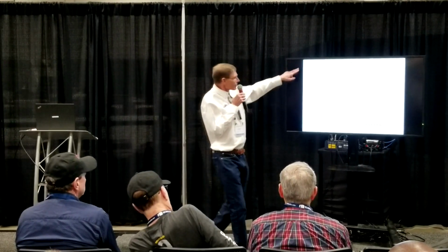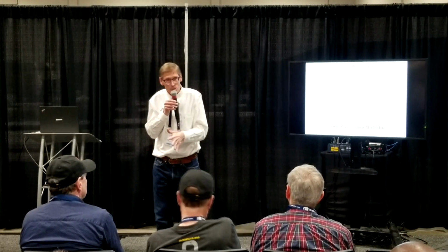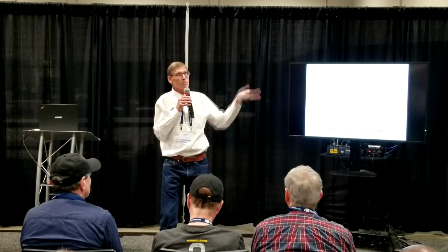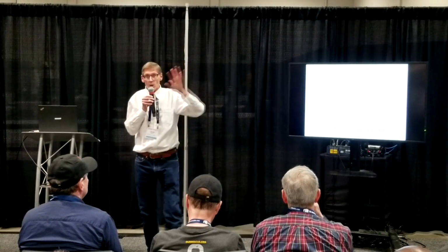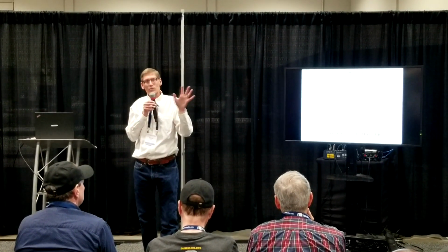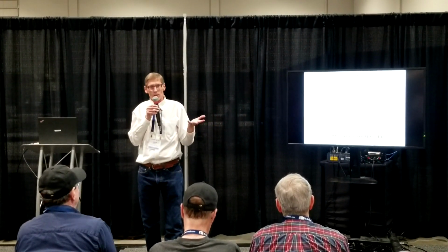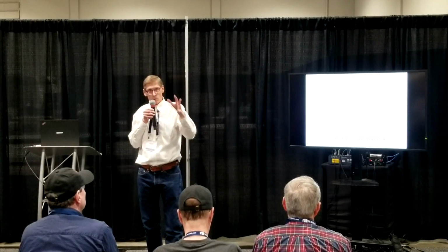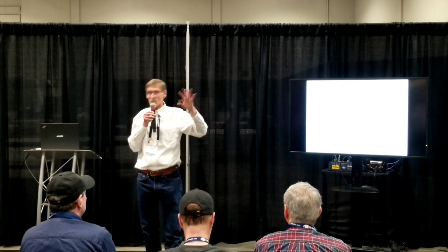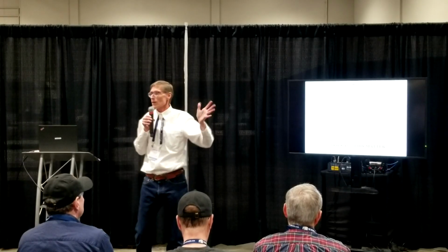So now we understand why our cables at high frequencies drop in impedance. We understand why they go up at low frequencies, because if VP is going to zero, that makes our impedance go up. Okay? We know how to properly characterize an analog type cable at low frequencies using open short, so that's a realistic way to help us understand what our cables are doing. We know what those numbers are comprised of. We have to have R, L, and C. Measurement gets R and L, or the swept characteristics, and the other one gets the X sub C, or the capacitive characteristics. So we roll all those together, and that generates our impedance.